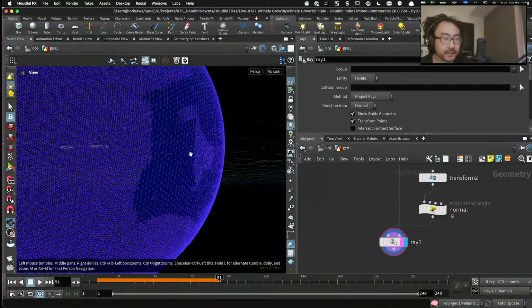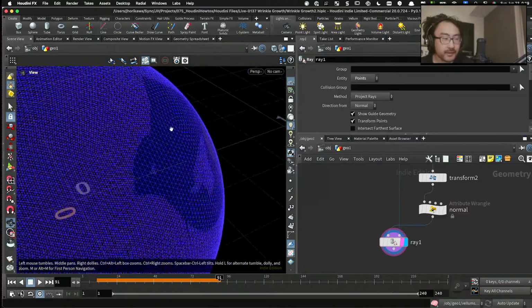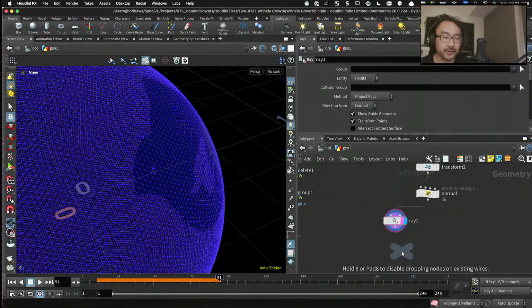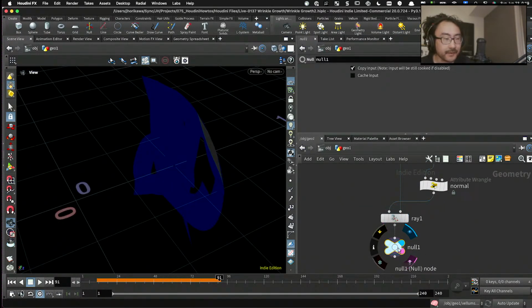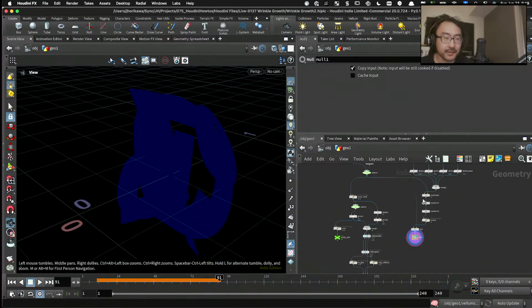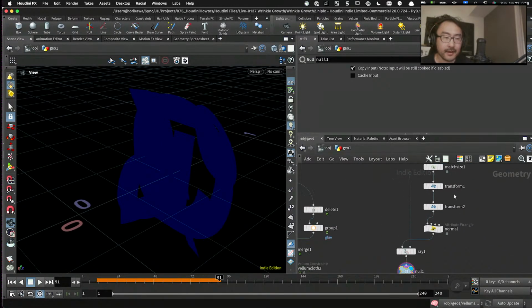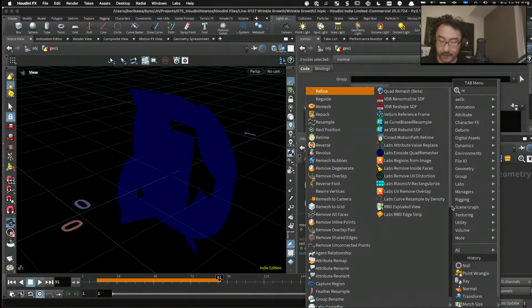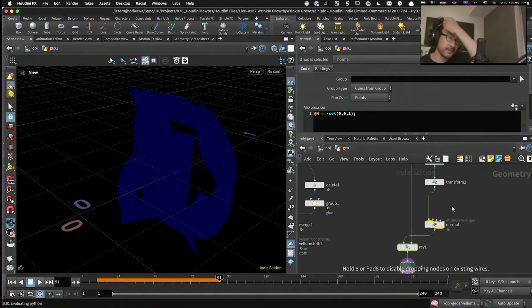Now there's some problem with these, some of these edges are not projecting correctly. That is because I don't have enough edges for some geometry, so I think I need to remesh these to have enough edges.